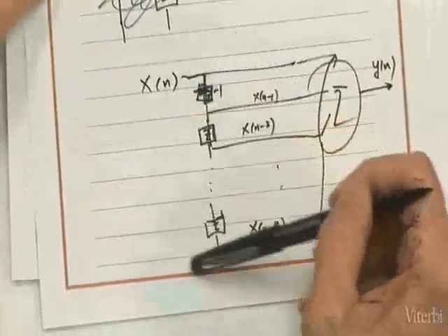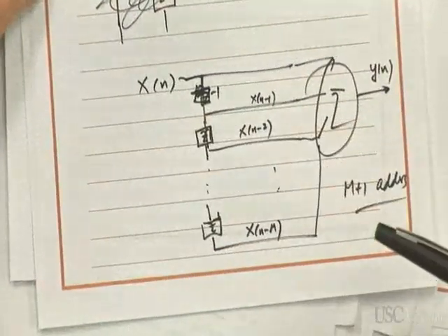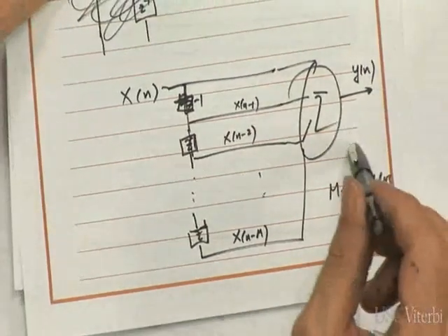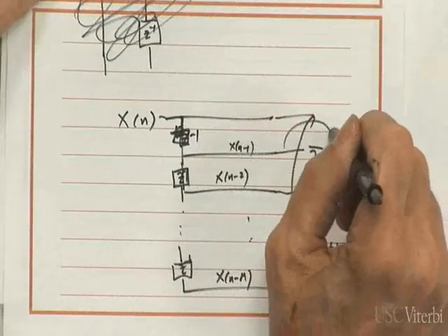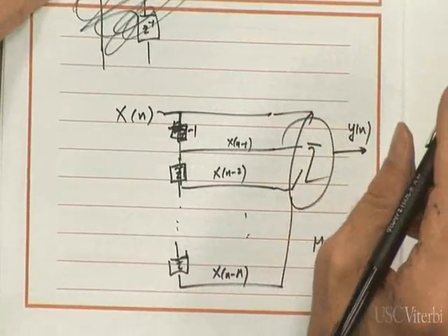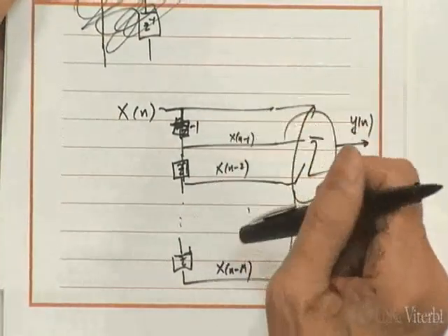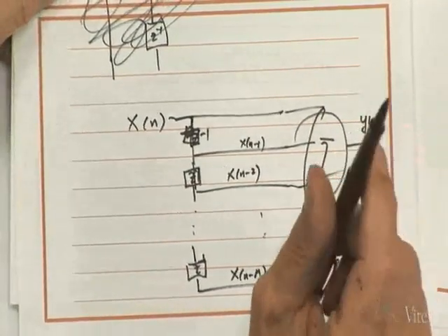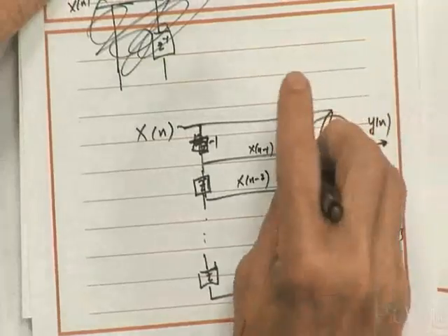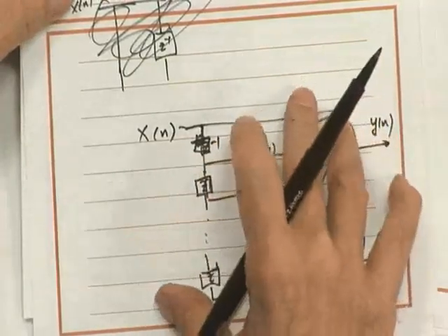So you mean down here, you have a time series that you want to filter, and then you have to define a window size, and that size is M, right? Yes, that's correct. So in order to get the first filtered point, you need M samples. That's correct. So you will incur a delay.